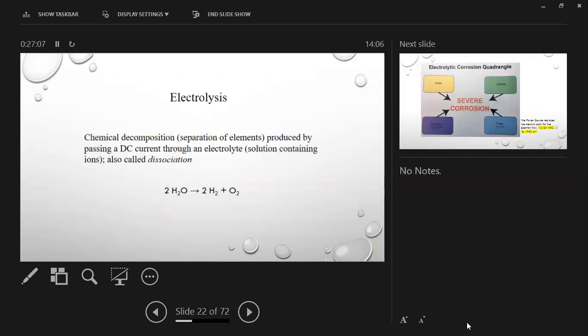Now, electrolysis can be a byproduct of straight current corrosion, but electrolysis is defined as what happens to the electrolyte. Corrosion is what happens to the metals. So when you see a prop or something eaten up by galvanic corrosion, it's not electrolysis.